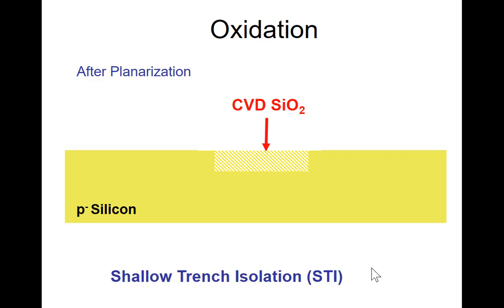But this one is controlled. You first use dry etching to cut a trench in like that, and then you deposit your silicon dioxide into it. So now you have a very nice, well controlled shape. It's not perfectly vertical down, but slightly tilted. The top side is typically wider and it goes down like that.